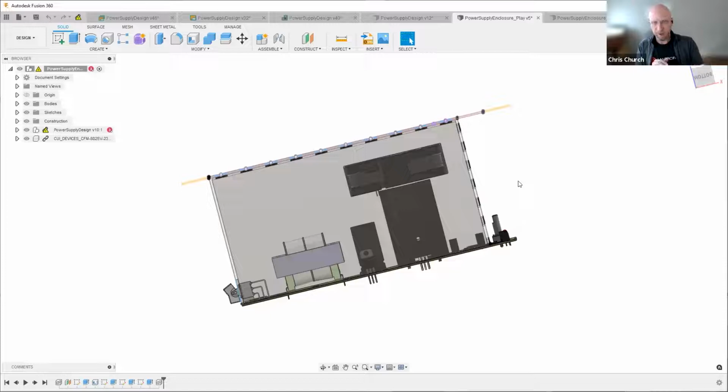We go through a series of process. We do SMT assembly, then the through hole devices are placed into location, and then we either go on to manual soldering or wave soldering or selective soldering, depending on the volume.